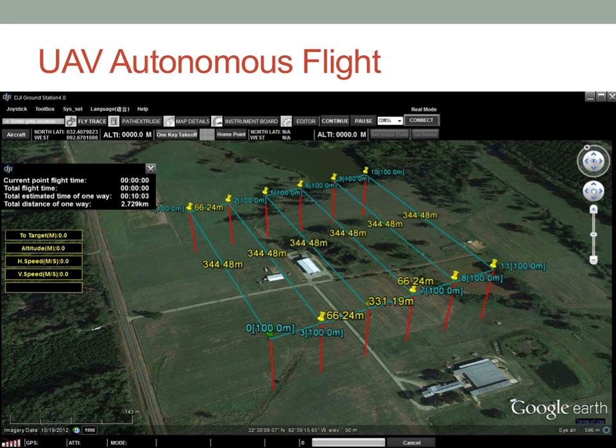All right. Another function of these is you can have autonomous flight, or an autopilot that you can set up. So here's a little screen grab of the flight planning software. You would pick an area and say, I want to fly this track at this altitude, at this speed, with this many flight lines. If you're unsure what those parameters might be, there's another module where you can say, I just want this ground resolution of photography. You calculate it for me, and it'll calculate the flight lines that flight needs to be. Then you upload that flight plan, those waypoints and that track, to the device.